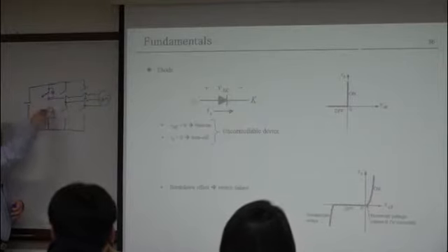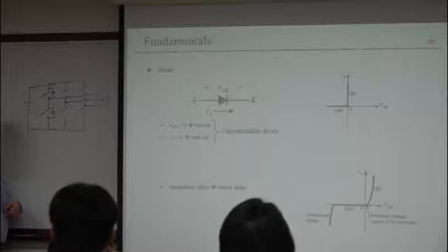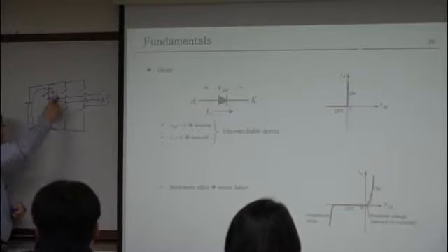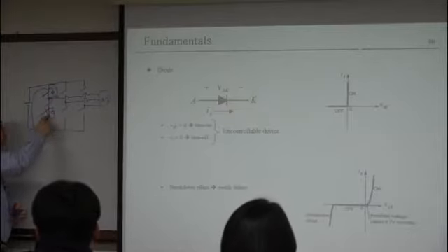Even if you turn off the switch, in transient you make a short condition because of the reverse recovery. What is reverse recovery? You flow current like this, right? Then you turn on the switch. For example, this is turned off. You turn on, and your reverse recovery makes the reverse current. Then this is what? Short circuit.